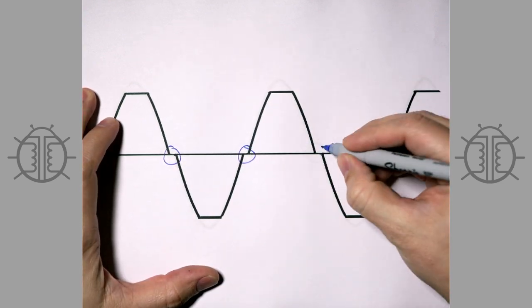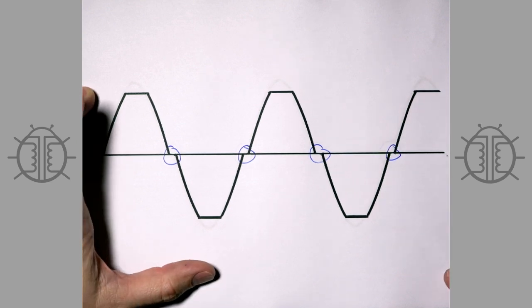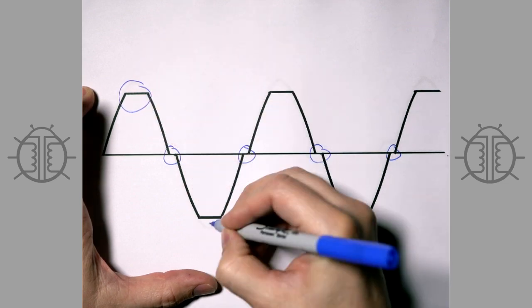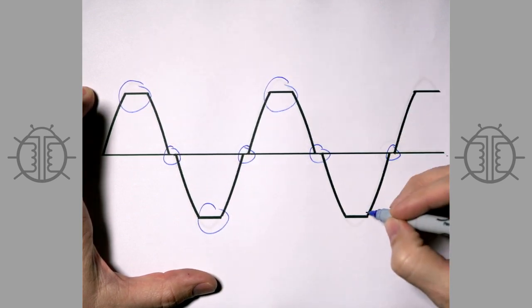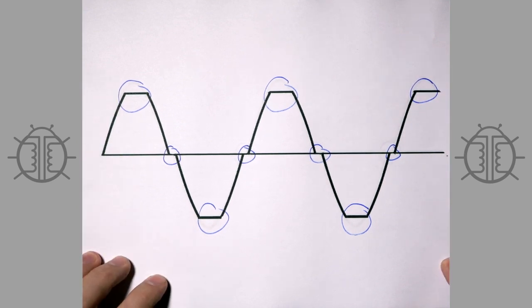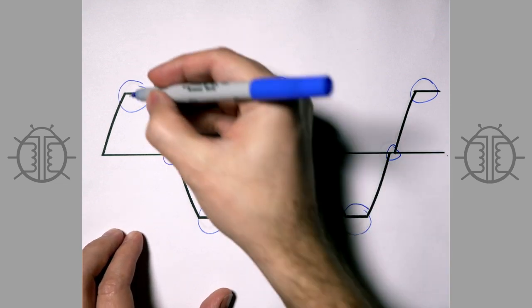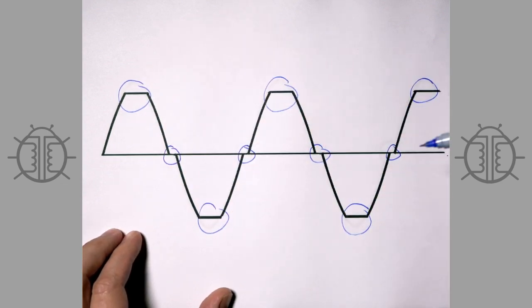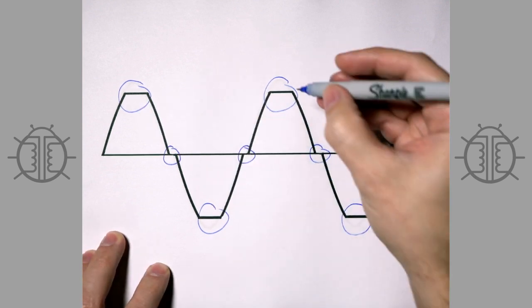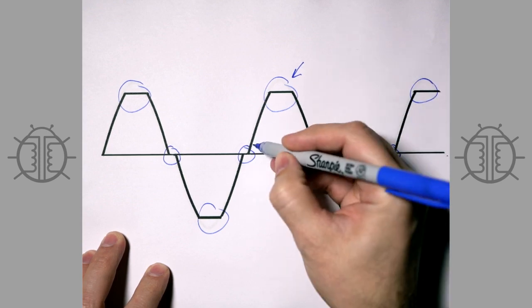Because once you reach 0 volts on an AB1 capacitively coupled output stage, you're going to clip here, obviously, and you're also going to have the crossover distortion. So this is what it's going to look like. This is undesirable. You don't want that. You're always going to have clipping with an AB1 capacitively coupled output stage when you reach 0 volts. But this kind of clipping is preferable to this and this.